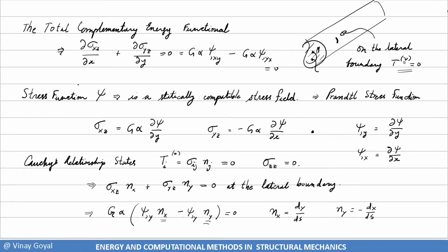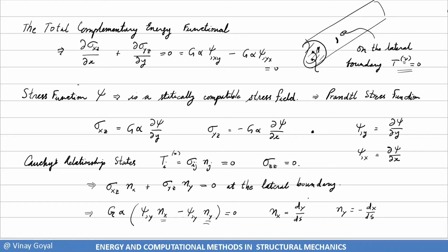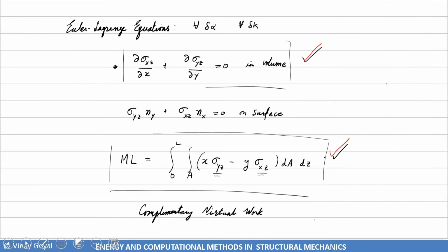So here, I've done multiple things. I've already shown you very powerfully, actually, very cool, by creating this Prandtl stress function and coming up with this function, I actually satisfied this one exactly, and I satisfied that one exactly. You can see that there. So that's amazing.